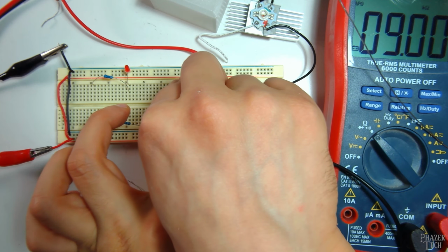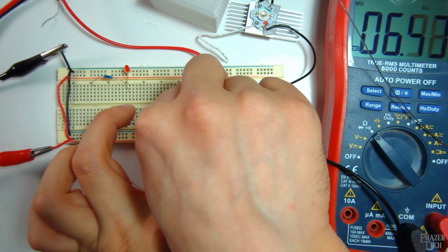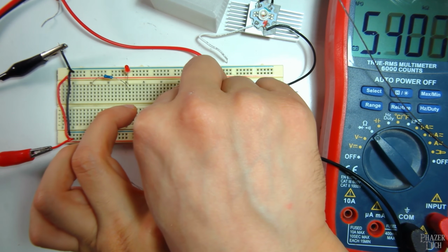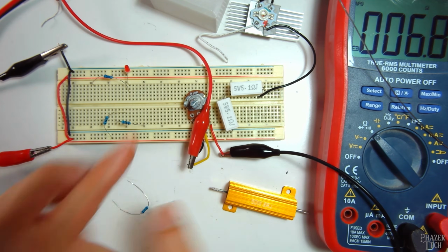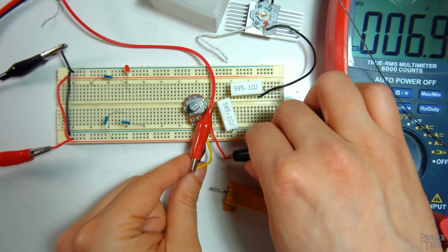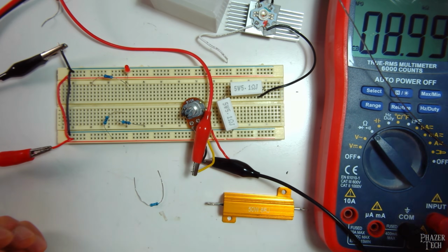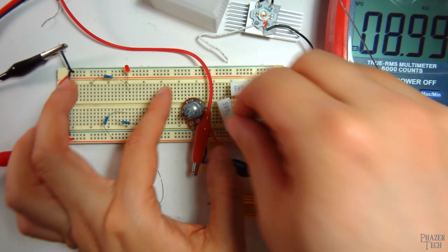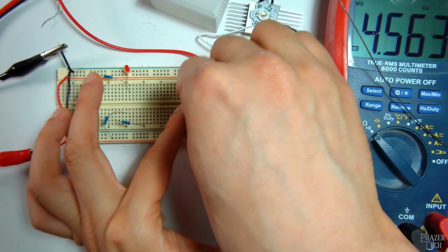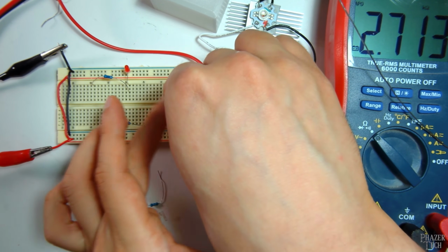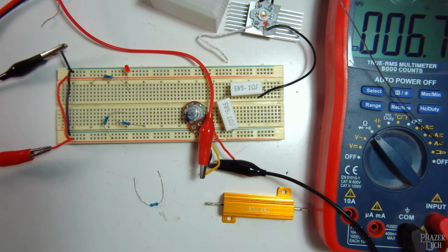And now as I move it, you can see it decreases. Now I'm about almost halfway. And now if I keep going all the way, we're now at basically 0 ohms. But now if I were to switch this probe to the other side, so now we're measuring the other resistor, we now see that that's almost 10K. And as I sweep the knob across the other way, we'll see the same effect happening where the resistance on this side is diminishing and it's all being shifted over to the other side of the voltage divider.